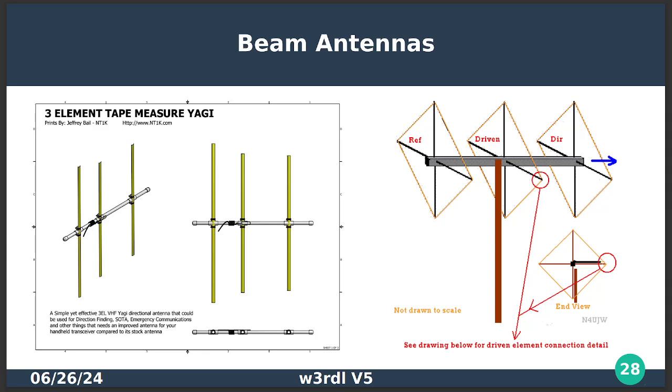And each of those loops, well, your driven loop is a full wavelength. That's one of the differences. Okay. Everybody get that? So these bars in here are non-conductive. All they are is being used for spreaders, and the lines going around here are a wire. So instead of having just this flat piece here that's doing it, you've actually got a round part. And this driven element, you said, is a full wavelength. Okay.